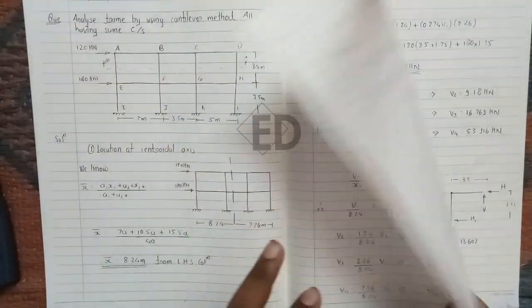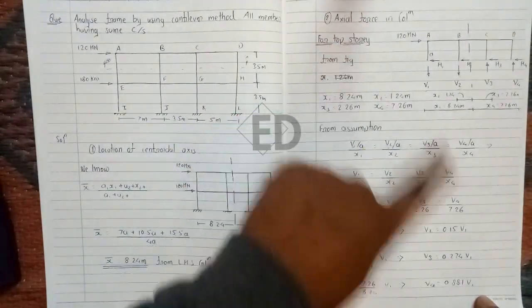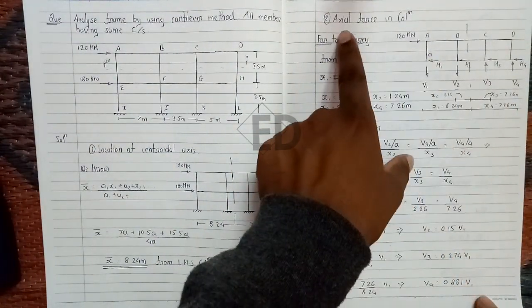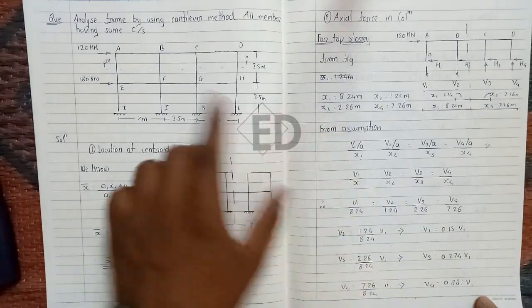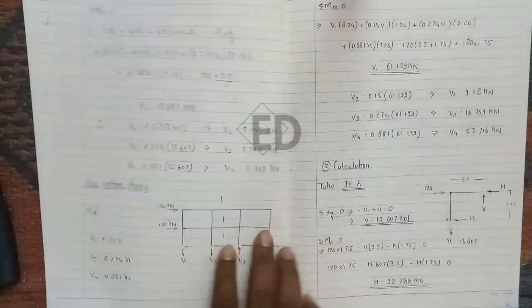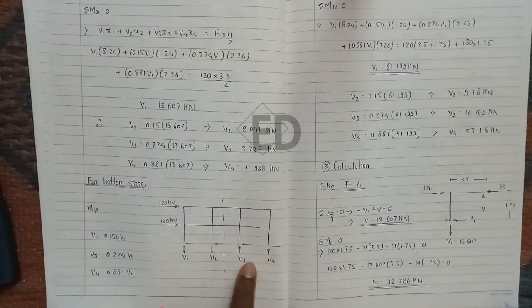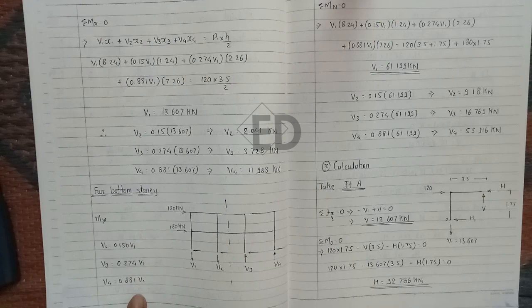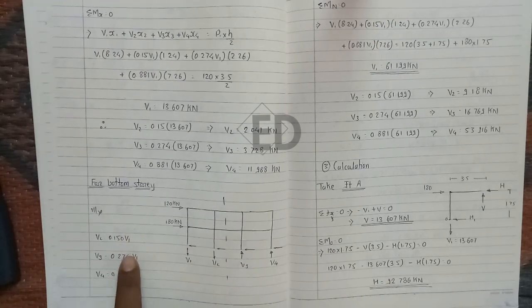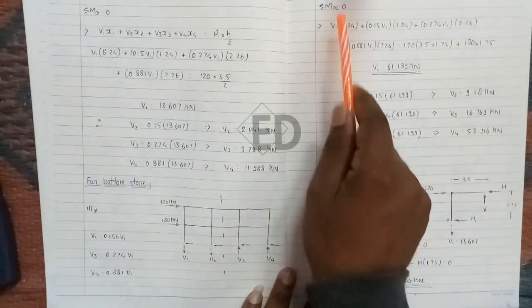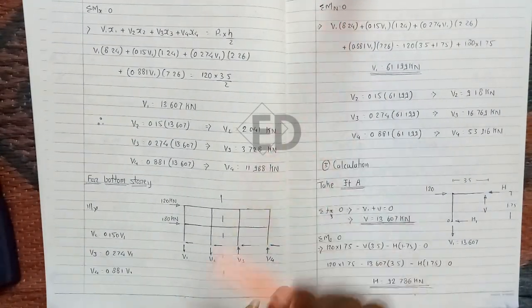So it is so simple. Likewise, we have calculated all the axial forces in the column of the top story. Now the same calculation is made for the bottom story, that is, the section passes through the point of contraflexure. So these are the forces in the column, same as the previous one, and here we take the moment at this point,